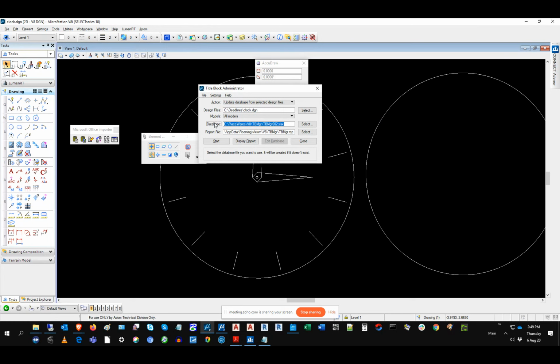If you're using tags, it doesn't require any setup. And in most cases, tags are the way to go because those tags are tied to the project-wide metadata for things like sheet numbers and sheet totals that people need to keep track of, and that ProjectWise helps you keep track of. When it comes to tags, Title Block Manager doesn't need any special setup or processing.